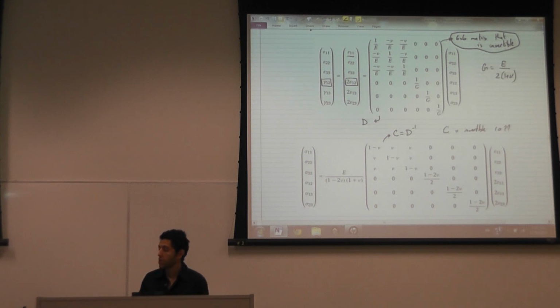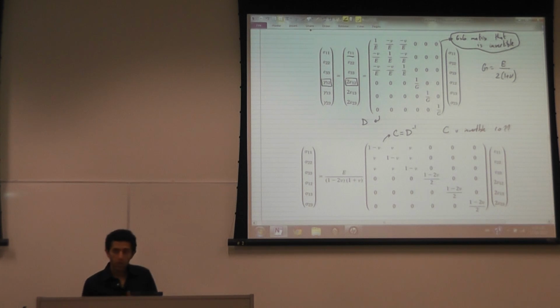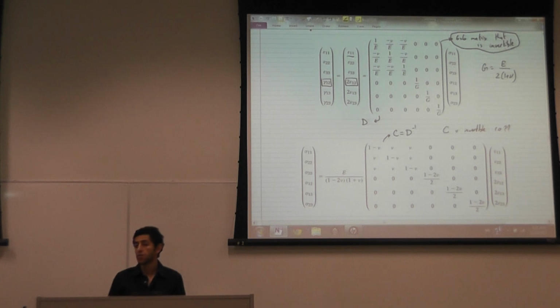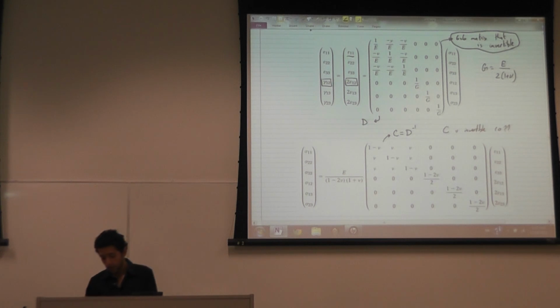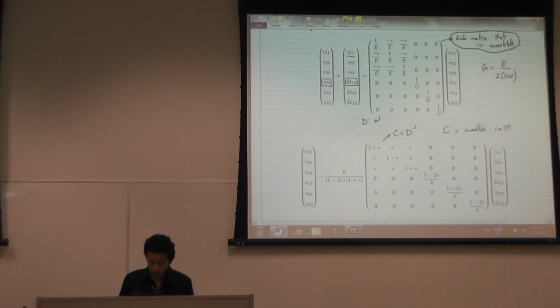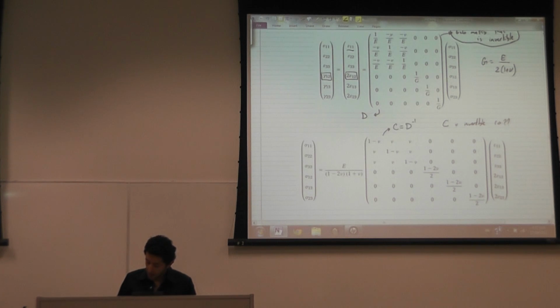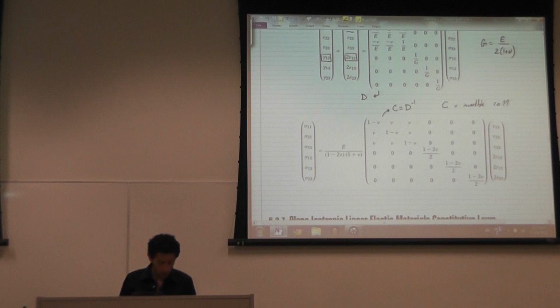Or maybe there are other materials that have, for a certain state of stress, different states of strain, but then you have to be looking for different solutions, corresponding to the possible states of strain. But for our numerical algorithm to work, it's better to have a one-to-one relationship between the stress and the strain, and this is the inverse of that relationship.